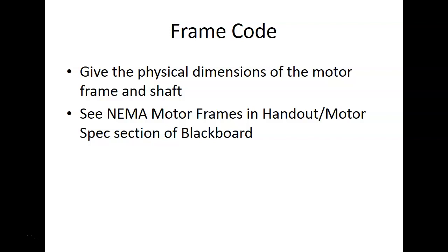The 240 still has a little problem, but they're still standards. It depends on what plug the electrician puts in when wiring your house, but it's still a standard plug. So now when you go to Lowe's and buy a dryer, they don't come with power cords anymore because they don't know which NEMA 240 plug is in your house.